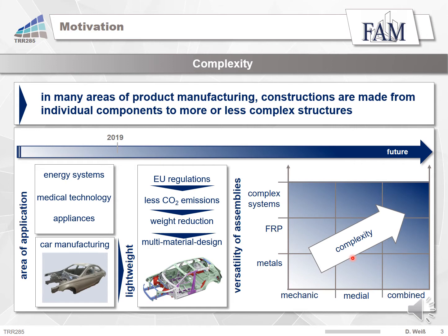A joining method that can join different types and coated materials without additional heat input is clinching. Furthermore, you don't need a joining element, which leads to the desired result of cost and weight reductions. The clinching process will be explained on the next slide.